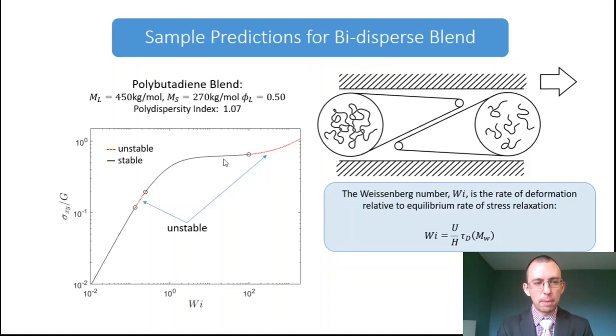Well, the thing to remember is that for shear-induced demixing, let's start from flow-induced fractionation phenomena. All chains in the system want to get themselves from regions of high shear rate down to a region of low shear rate so they can be less stressed. Okay. But which chains can actually do it? All chains can't migrate in the same direction. Some have to migrate one way, and some have to migrate the other way in order to fill in the space left behind. So the direction of migration is determined by which of the species has the stronger driving force behind its migration.